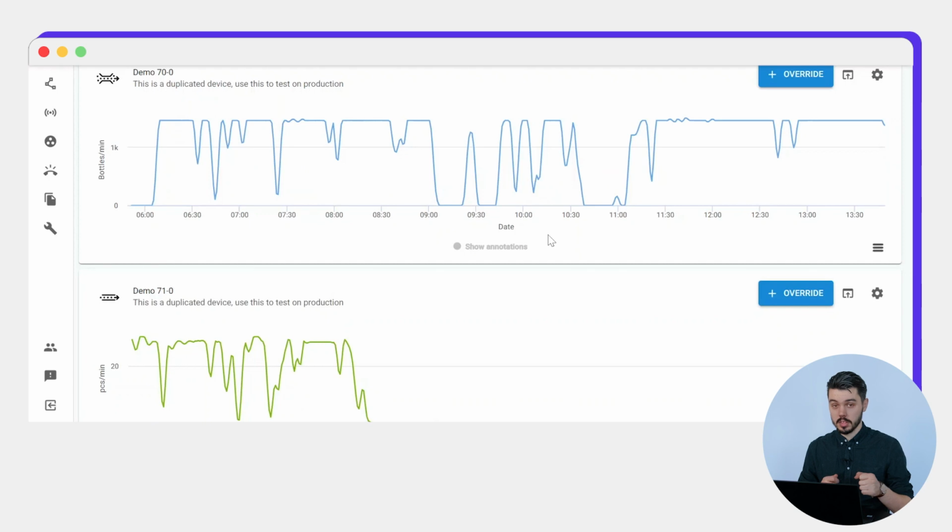Level 4 is then the next stage we're going to look at. And during this level, we want to actually start analyzing the scrap we're experiencing on the line and the defects. Because once we understand that, we can analyze, once again, linking into those product issues. Maybe there's certain quality controls or operator training that are causing us to lose more product. If once again, certain shifts experience more scrap. But also we can add in sensors to different points of the line where we know items get scrapped for specific reasons. And then you can see, right, I'm losing 50 products every shift for reason X. So maybe there's a major default or a major issue with operator training that we should look to address.